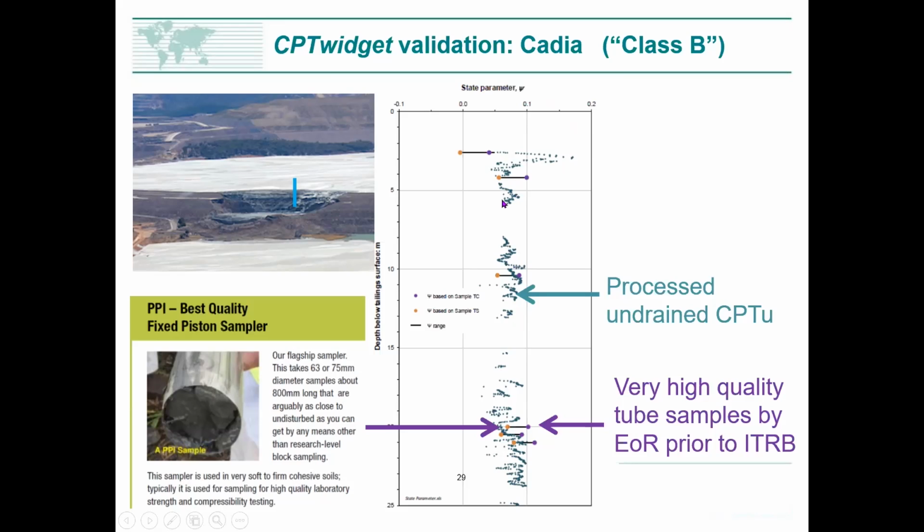The reason it's not a continuous line is because it depends whether it's drained or undrained. So we don't use a drained calibration if that part of the sounding goes undrained, and vice versa. So this is the bit that's relevant to what I'm about to tell you.